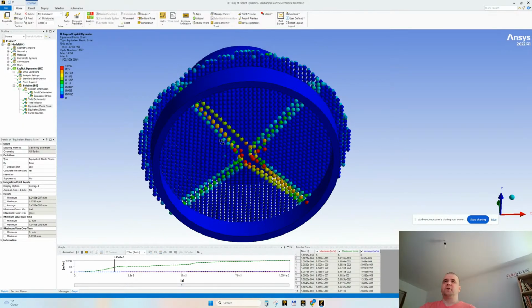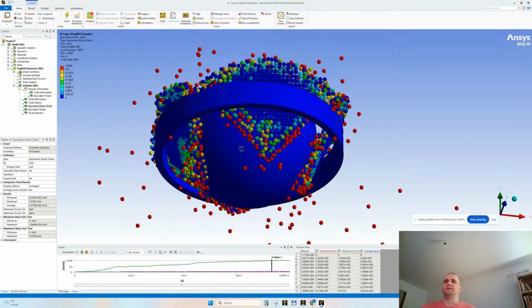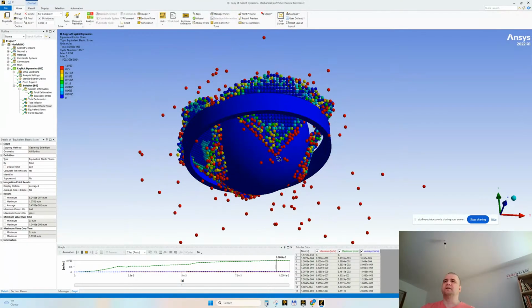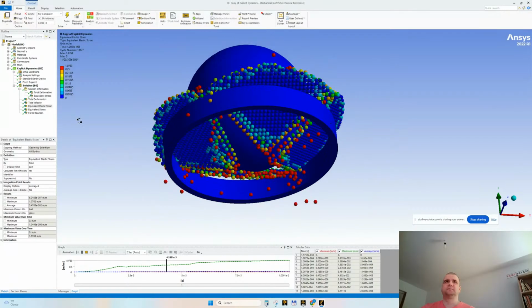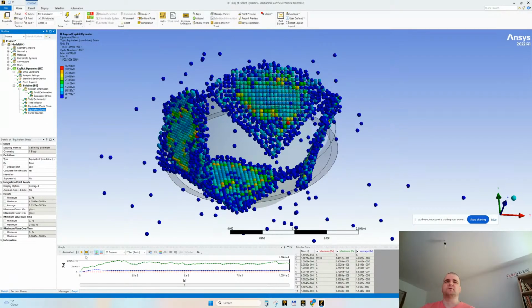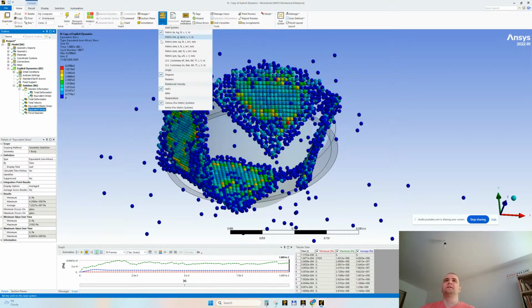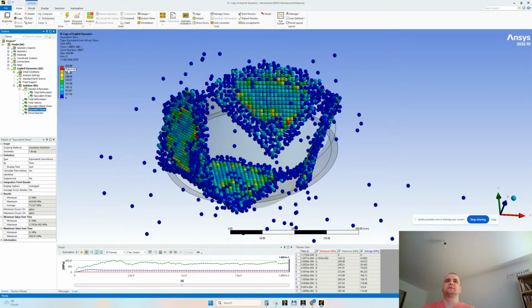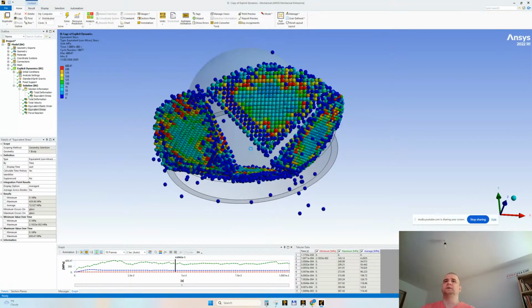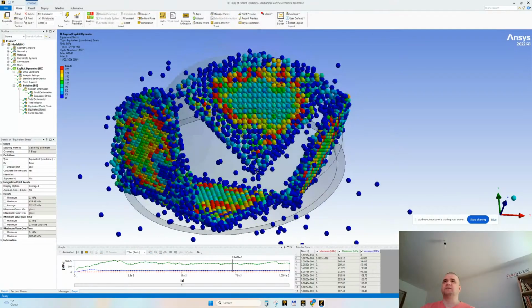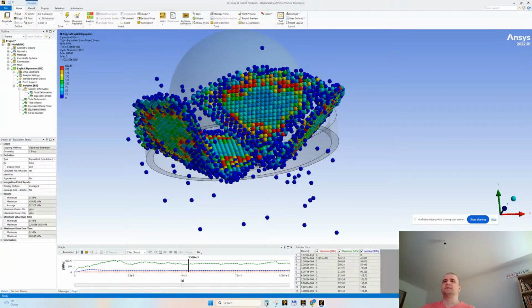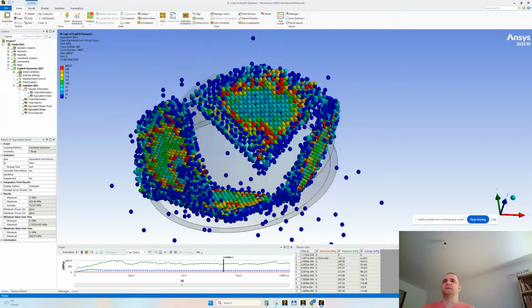And here the red points are not the inertia points that we switched on. These are shards, yeah, glass particles. And the stress, oh, it looks so nice. Let's make the stress in megapascals. And maybe assign 200 here. Oh, it's so nice. So here is an example of using SPH for brittle fracture.